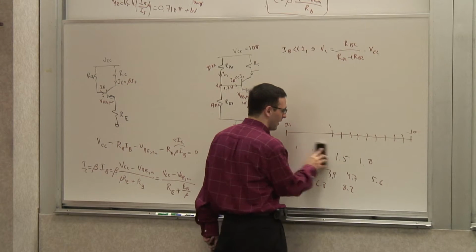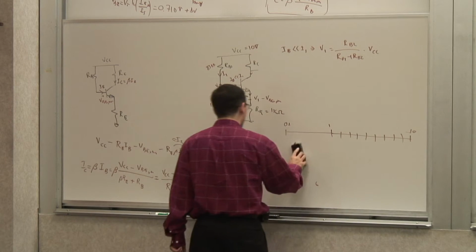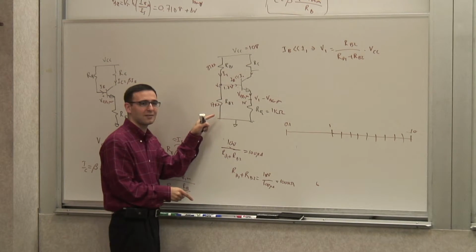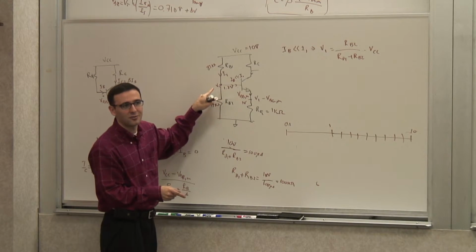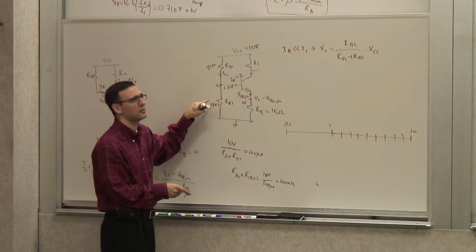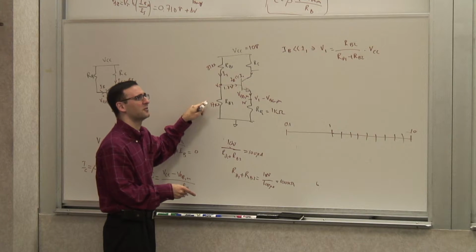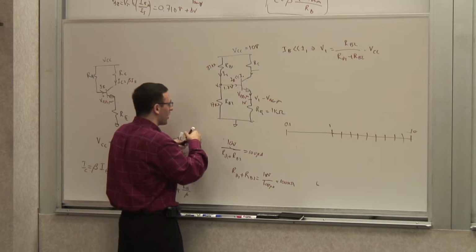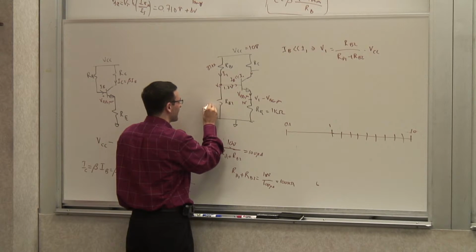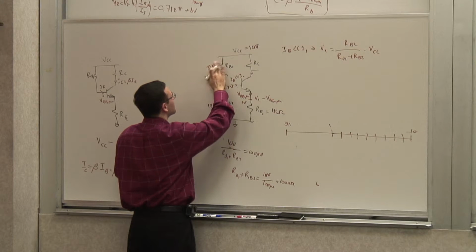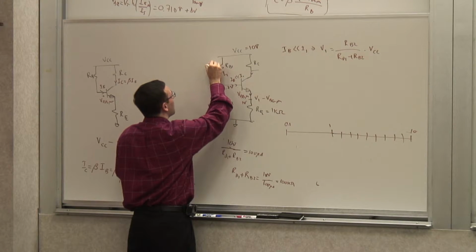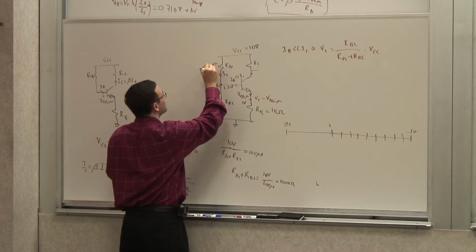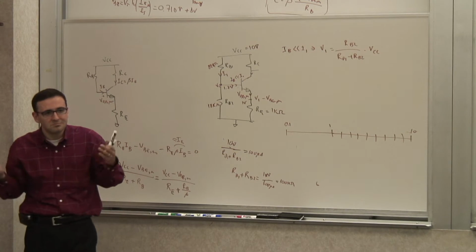That's the point. Of course, you can try to make exactly 1.7 by combining different resistors, like 1.5 and 300 kilo, or 200 kilo, 100 kilo, or something like that. But let's not bother about it. I think it's good enough. So this is 18 kilo, this is 82 kilo ohms.